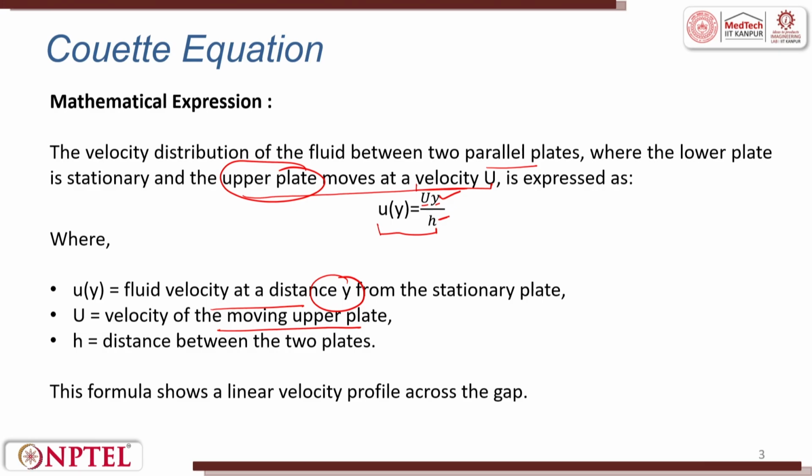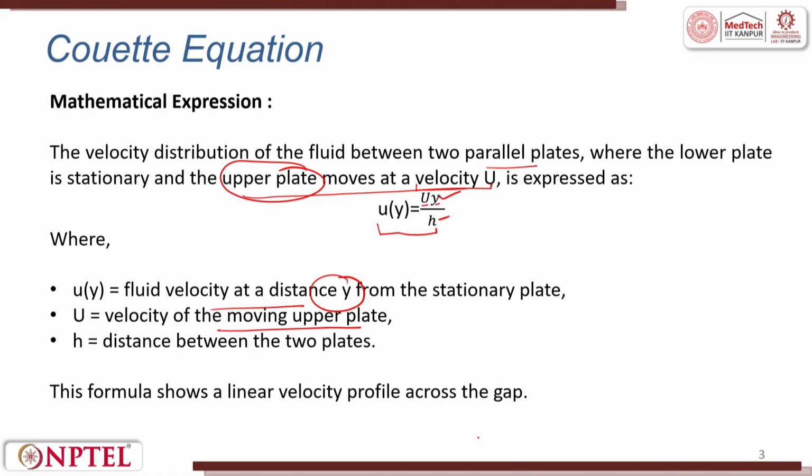The Couette equation has real life practical applications such as journal bearings. In bearings, there is always a gap between the bearing and the ball, with lubrication between them. When it is running at very high RPM, maybe 10,000 RPM, the Couette equation determines what the distance should be between the ball's outer surface and the bearing's inner surface. Other examples could be the hydrodynamics of the earth's crust, and certain applications in chemical reactions and chemical engineering.